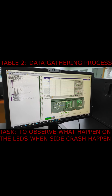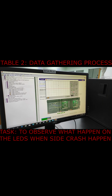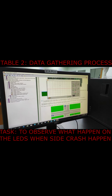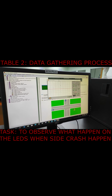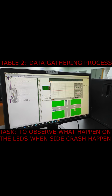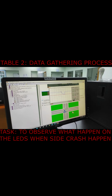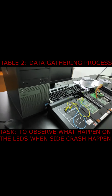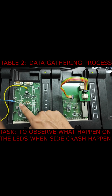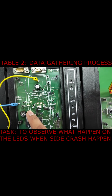Okay, once we install the wire, now we will conduct the simulation. It's quite a straightforward simulation. So we just put it and then scroll down. Okay, now you select this button, select it. Okay, the LED is bright, the LED for the belt is on, the LED for the side airbag is on.